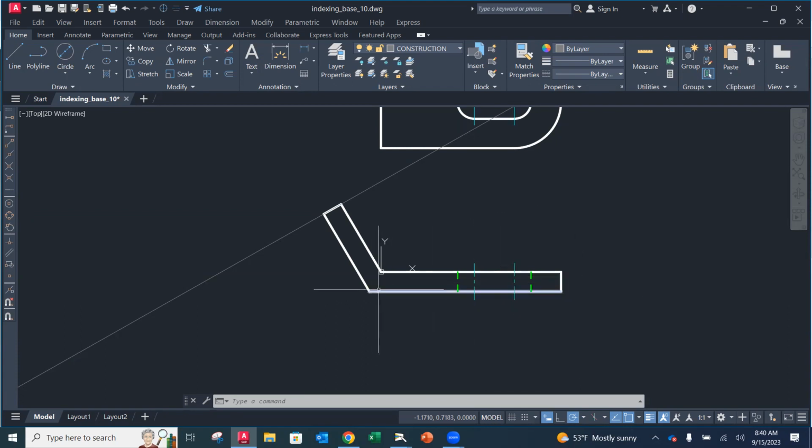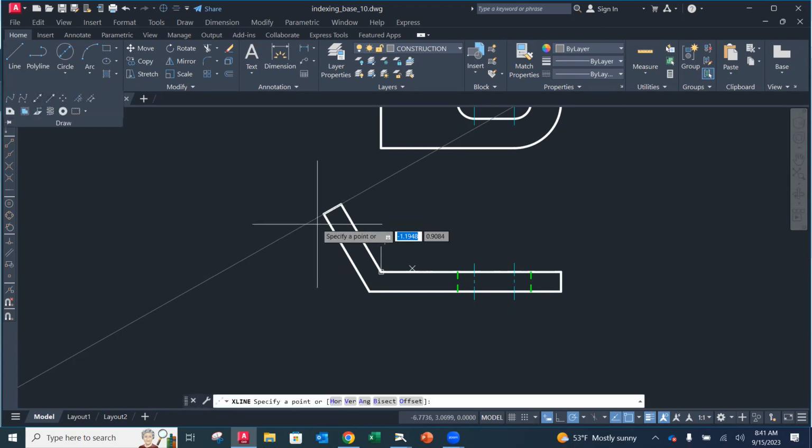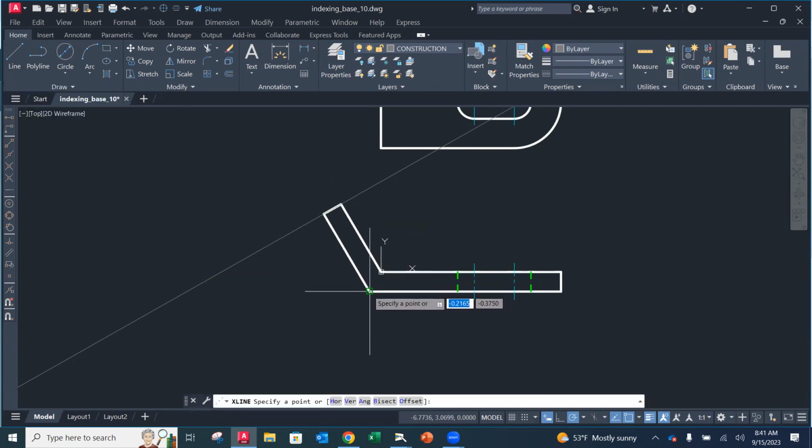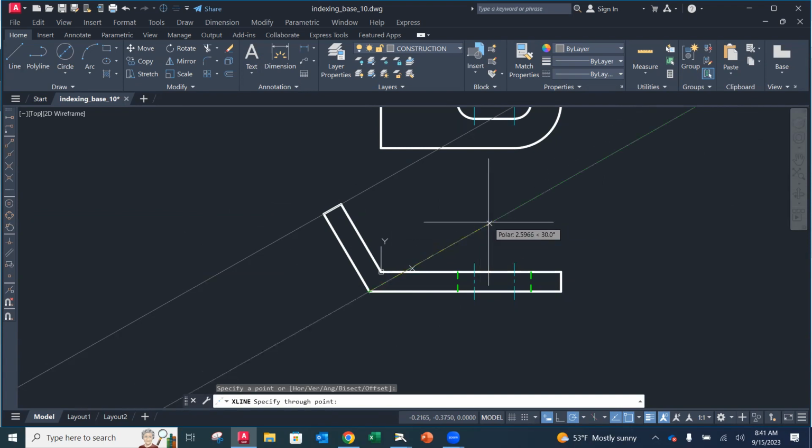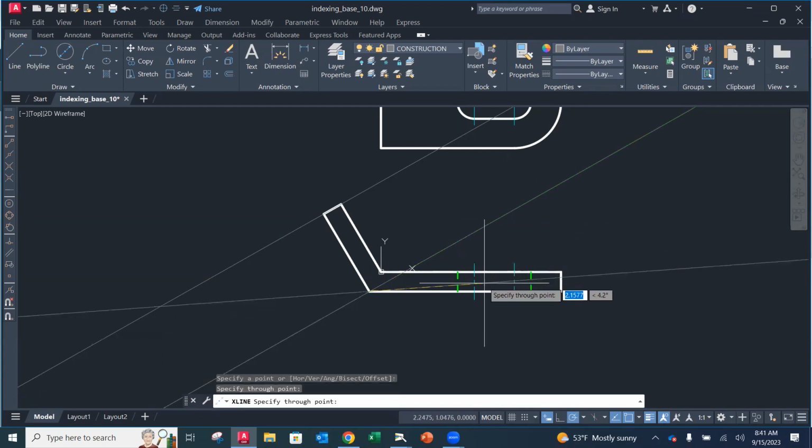By putting that in place, now it's going to snap to every 30 degrees on our angles, which will come in handy here for us. So I'm going to go to draw construction line, and I'm going to grab this corner right here, because I don't have that diagonal to go along. So I'm going to click it, but it's going to be at the same angle. And now notice that when I hit that 30-degree increment, I can see it's parallel to the other one. So I can just click anywhere in there.